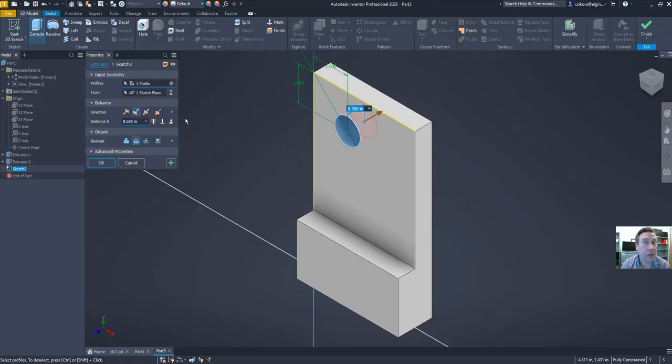Now change occurs all the time in design. Someone might find, oh, 0.5 for that plate is too thin. Let's make it 1 inch. They go ahead and they change the thickness of the plate, but your dimension, they miss it. It still looks like the hole's there when they look at it from an isometric view, but they didn't look through it to the top or the front, and all of a sudden part gets made, maybe millions of parts get made, and then they realize when they try and put a bolt through it, oh wait, this isn't the through hole, what happened? Design intent is to kind of plant a seed.